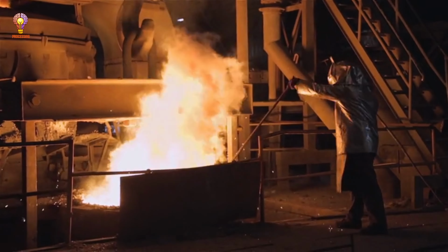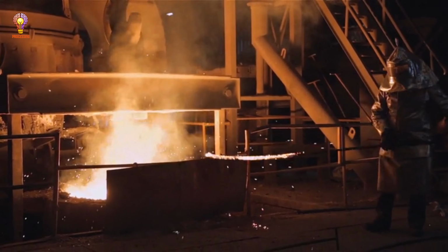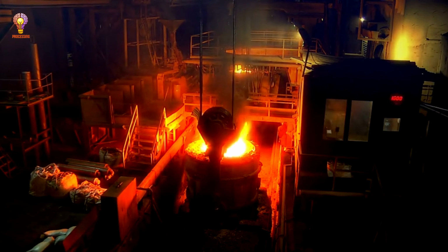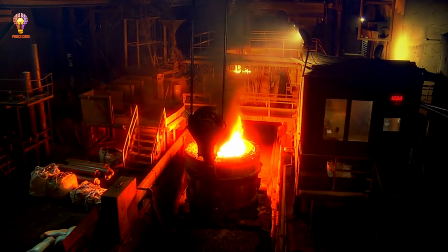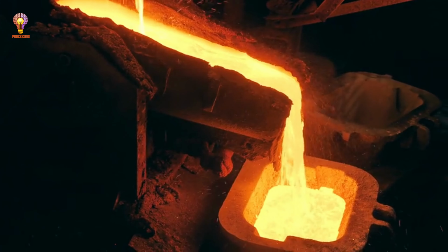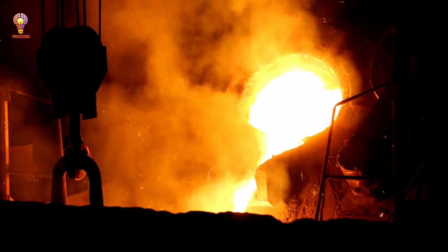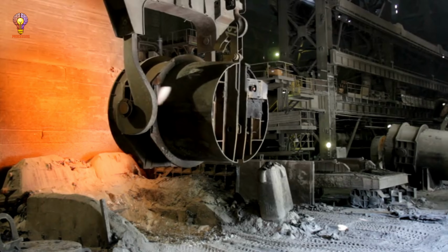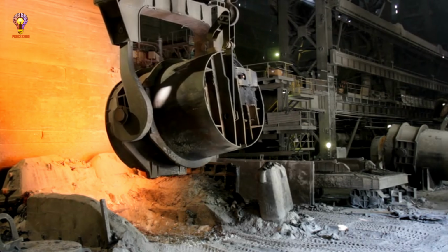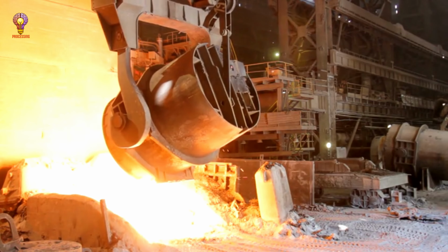1. Emerging steelmaking technologies. Molten oxide electrolysis. One of the cutting-edge technologies being explored for low-carbon steel production is molten oxide electrolysis. This process involves applying electricity to molten iron ore, which eliminates the need for coke as a reducing agent and produces oxygen instead of carbon dioxide. This process shows promise as it could potentially replace both the blast furnace and electric arc furnace, making it one of the cleanest ways to produce steel in the future.